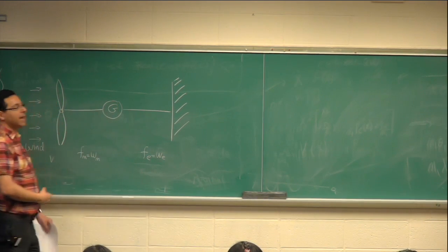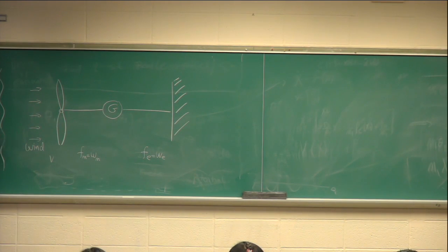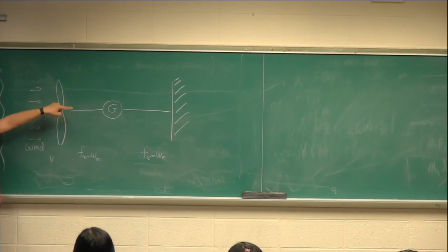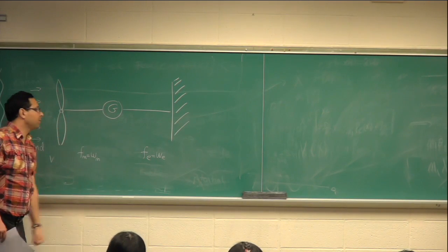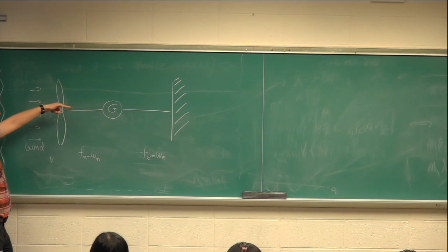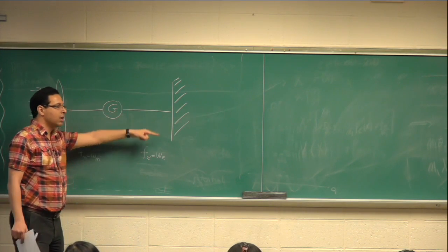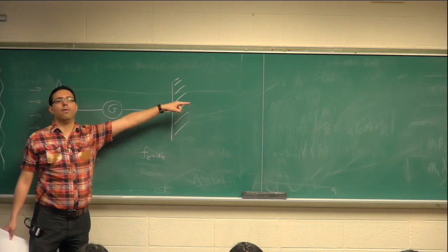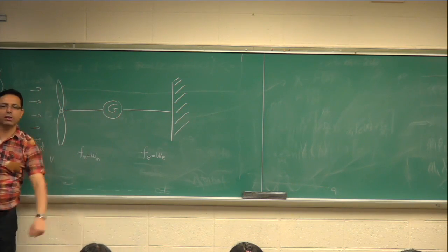These things are related. So you apply some wind, you hope that gives you some mechanical frequency, or rotation, and a rotation in revolutions per minute, like 3600, is going to get converted to 60 hertz. Rotation here talks about sinusoidal signals over there, if you know the dynamics of a generator.